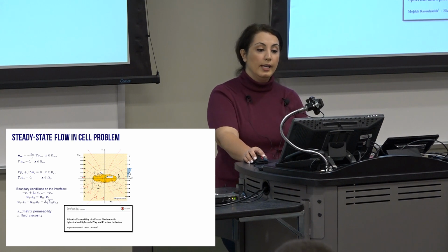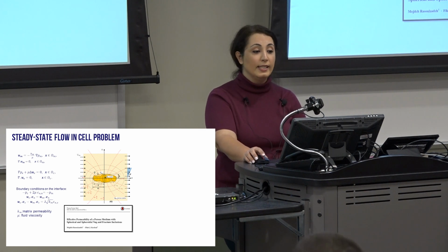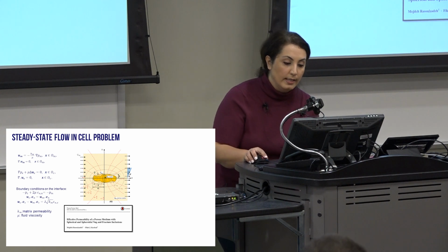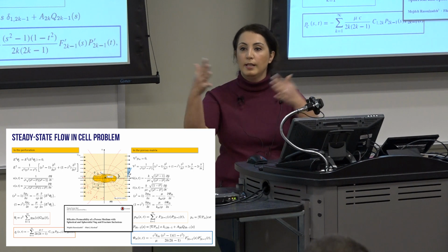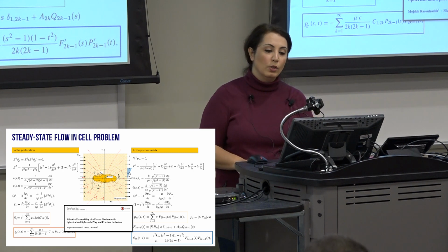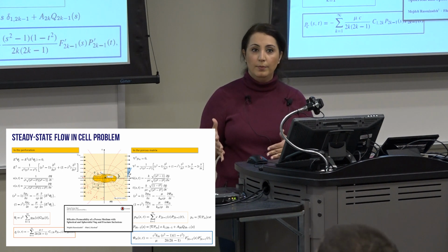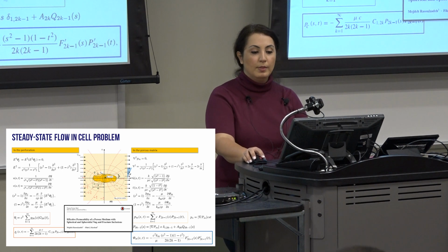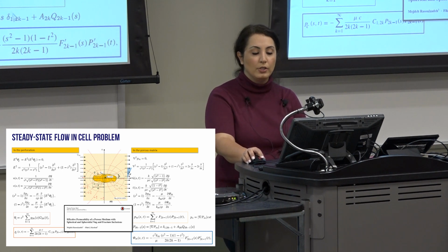One idea is actually to obtain the flow field analytically. This is a part of the work that I presented in this paper, and I obtained the solution to the coupled system of Darcy and Stokes equations in the perforation and in the porous matrix, in terms of some asymptotic expansion, some eigenfunction expansions.